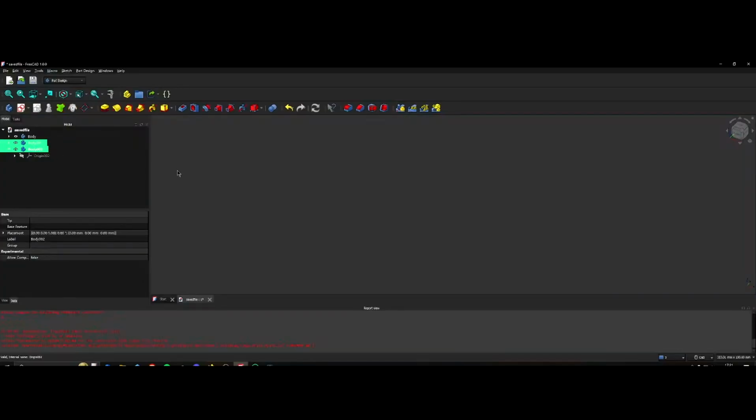Now, the thing that catches people out with FreeCAD when they first start is how an object is built within a body. Unlike some other pieces of software, there is a hierarchy of iteration. Every iteration of an object is built upon the last, and also, most features of an object are derived from sketches. This sounds like a bunch of gibberish, but as we go along, you'll understand what I mean. Let's actually move on to sketches now.